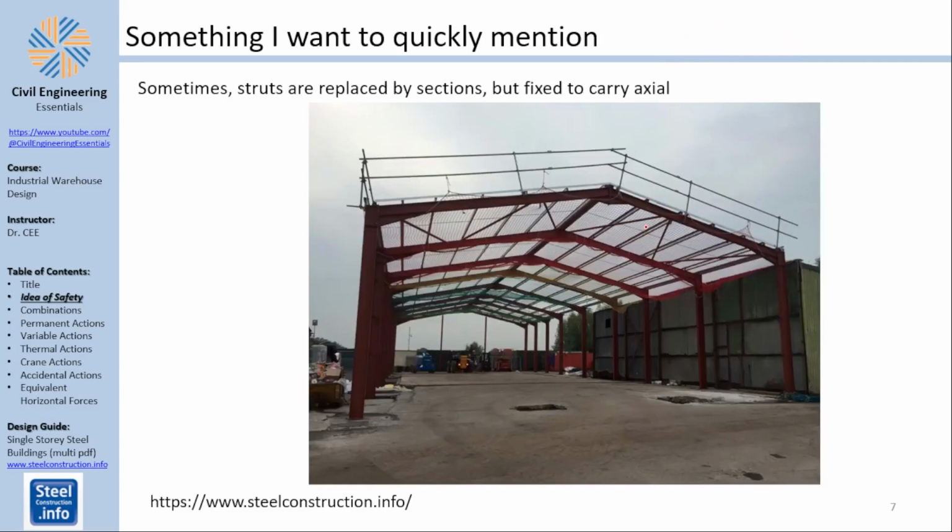It depends. Here is another portal frame where you do have an apex haunch, and the reason I'm showing those pictures is to show you how different portal frames can be constructed. You have the apex haunch here, the beginning haunch here, and you still have the stiffener here, which is typical because the haunch imparts compression. You can also see a purlin that seems to be connected to transfer axial forces, which should act like a strut. This is what I can see.